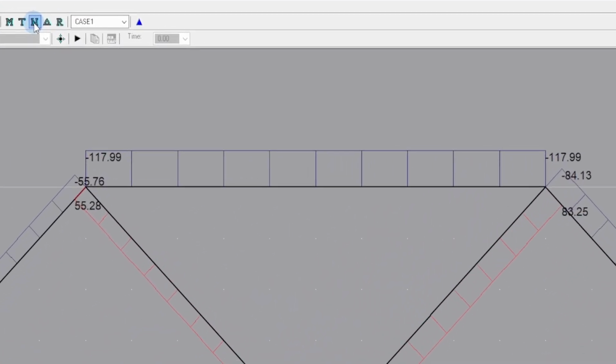LinPro gives 117.99 kilonewtons compression. Has something gone wrong? Perhaps it's rounding. What do you think? If you're thinking, no way it's rounding, then well done. The hand calculations were done using 4 significant figures, so rounding could not account for an error of around 2%. What to do next? Any ideas?